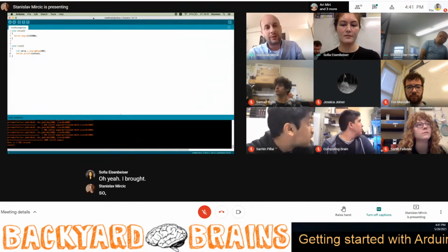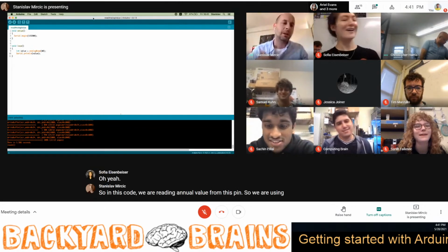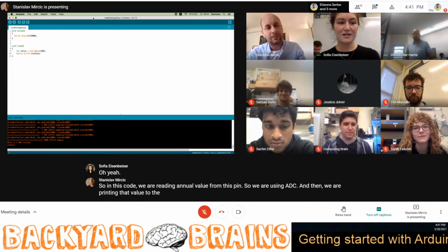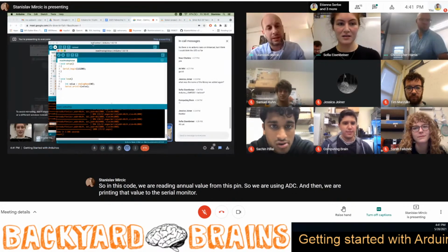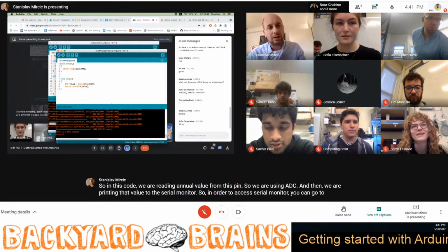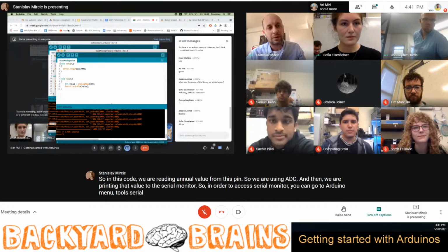In this code, we are reading the analog value from this pin, so we are using the ADC, and then we are printing that value to the serial monitor. To access the serial monitor, you can go to the Arduino menu, Tools, Serial Monitor.